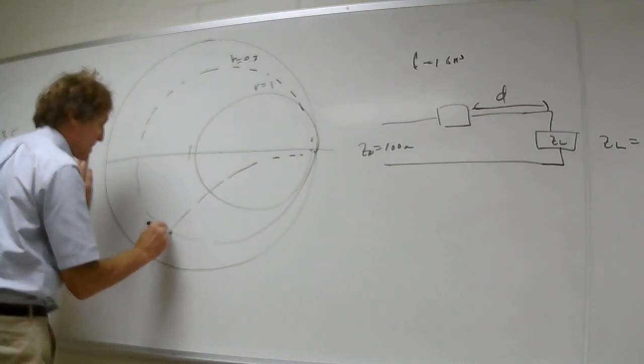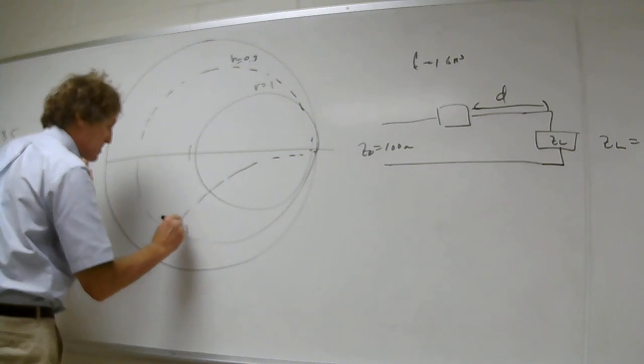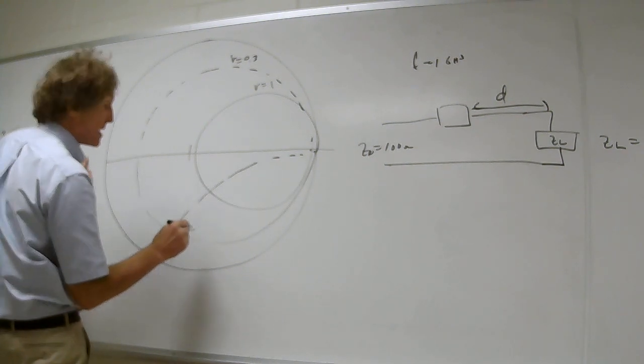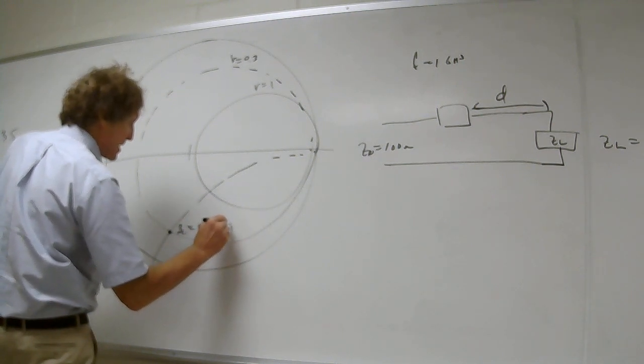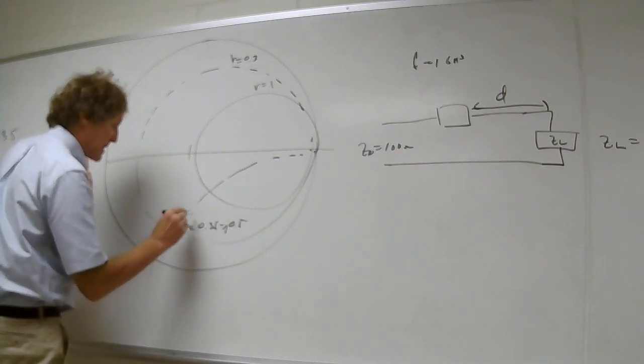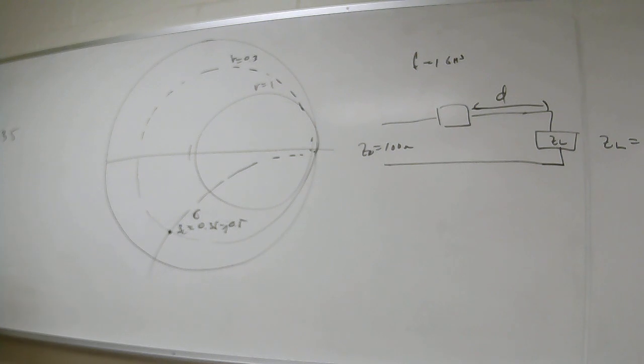So about here would be ZL. Take a look in your Smith charts, and that would be 0.35 minus j0.5. Can you all find that? Label it ZL. With me, class? Right. Next, take your compass. Hope you guys got good compasses.